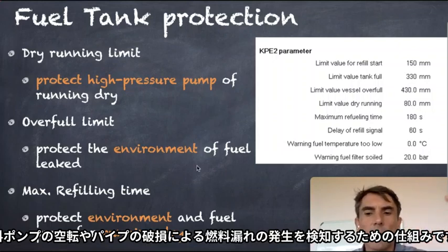That means the pump will run continuously and supply the fuel into the environment. To prevent that, we have a limit time that the pump must be stopped or the tank must be refilled within a time of 180 seconds.